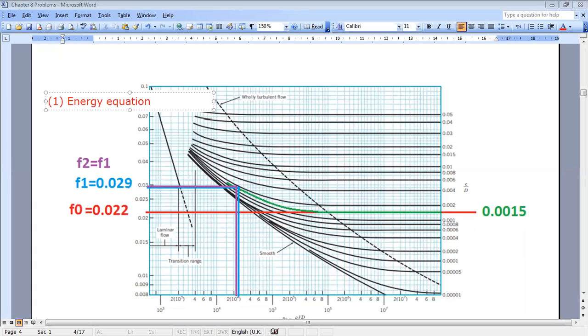Now, a second relation will be to write the Reynolds number equation, because Reynolds is rho V d over mu. So when you write Reynolds, you can relate Reynolds to velocity. Sometimes if velocity is given but diameter is not, I get Reynolds as a function of D. So it depends on the problem. Other equations that I can write, for example, is Q constant. Here, when I wrote that Q is constant, I got that V1 is equal to V equal to V2. Now, here, Q constant is already used for the energy equation.